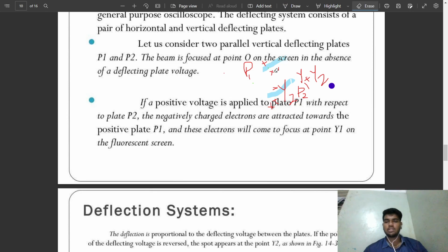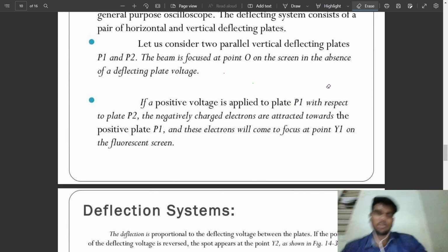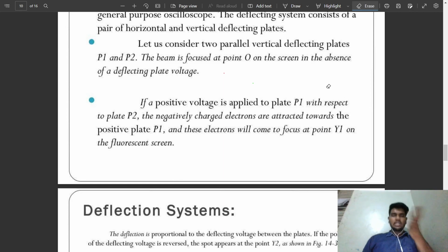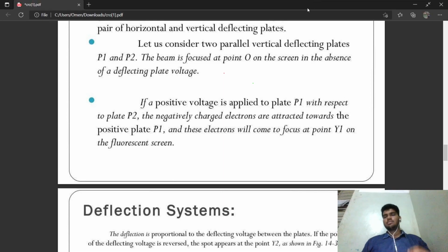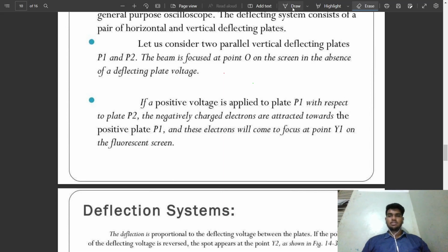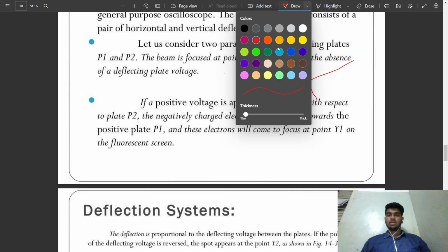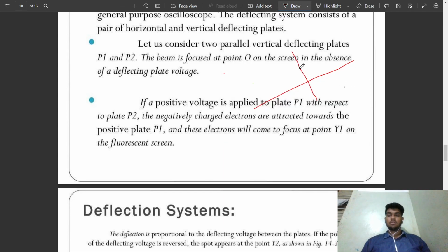Now we know that the signal is deflected vertically, so it is not exactly a waveform of a signal. It can be a DC signal. The vertical deflection alone only depicts the amplitude of it, but not the time frame or the frequency. Every signal has a certain frequency, so we need to check into that. For that we have horizontal plates. So this is the axis, and this is the vertical deflection.